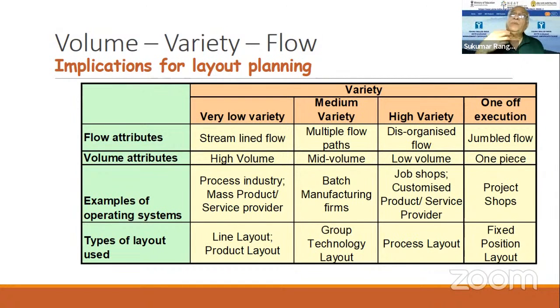But suppose I had a high volume of demand, I would probably have gone for a line layout. I have 4 basic varieties of product, but within that, the sub-varieties are very high. So I had to go for a batch manufacturing layout.